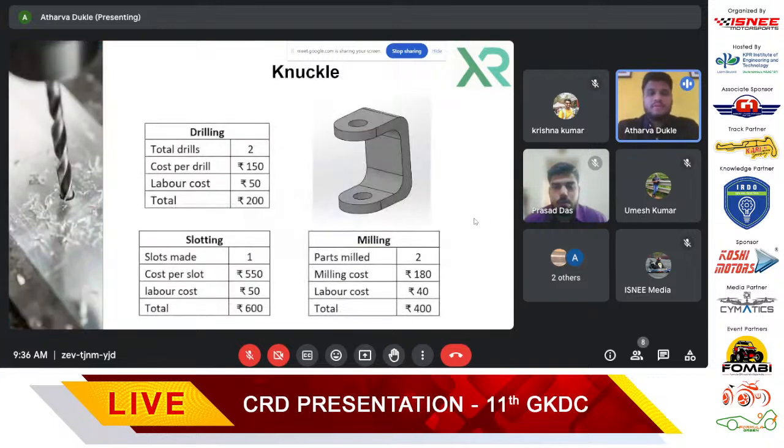Now, moving forward, we have the knuckle. The knuckle is the part which is welded to the chassis and it holds the stub axle within itself. This is one of the parts that we have made in-house. First, we bought the material from outside of the desired dimensions plus some clearances, which will be negated after we complete the processes. First we went with the milling process, after which we went with the slotting process and then the drilling process.